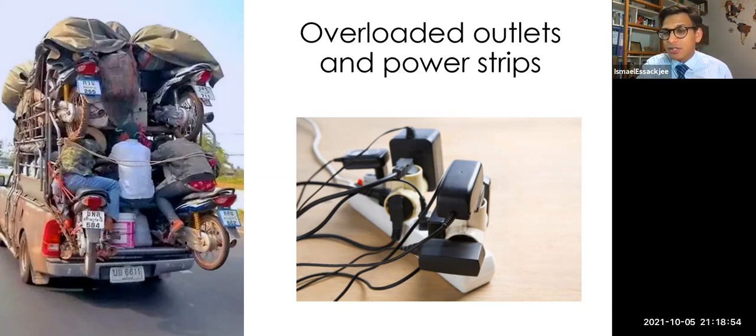And this one, as you see in this picture, is temporary, it should be temporary. This type of setup, this extension socket, should be temporary. But if you leave it like this for a long time, you will see it is dangling in there. It's not properly fixed. This is used for temporary use only. While it is dangling, it is moving in the socket, and it's going to create flashes and can ultimately cause fires.